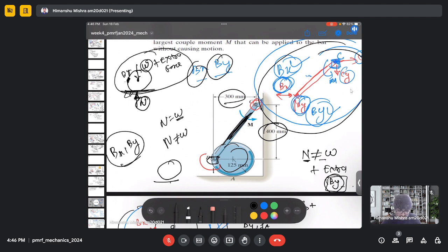So this combination of these extra forces and weight will give the normal reaction. So it is weight plus this external force, so it will come more than the weight, because we have another force which is due to this joint. So basically, there are reactions of the hinge joint on the wall transferred to that location.